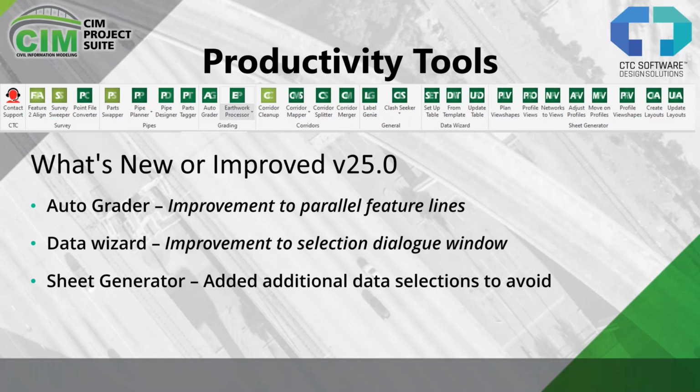But our biggest addition for 25.0 was that we added additional data selections to avoid. So now instead of just avoiding our PIs, PTs, things along the alignment, we can avoid, for instance, structures, manhole structures, pressure pipe appurtenances, and along with that, other things that might come in handy, blocks, COGO points, but we will get into that and I'll show you a few of those today.